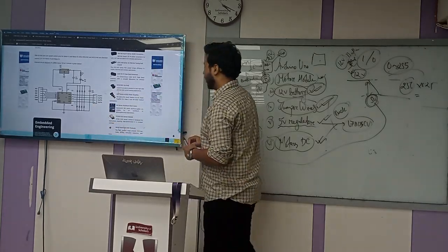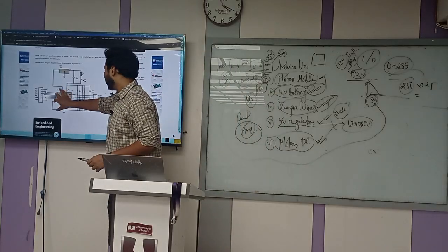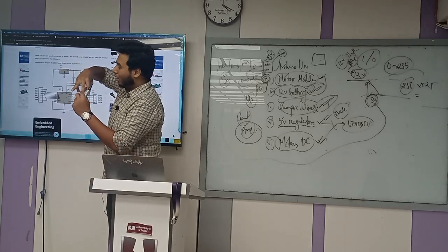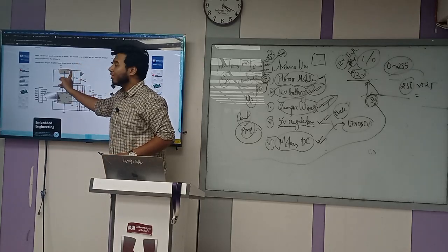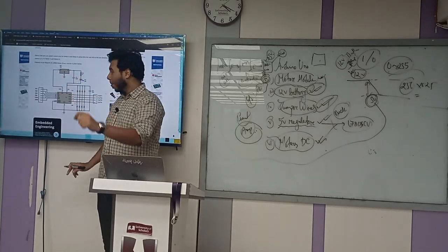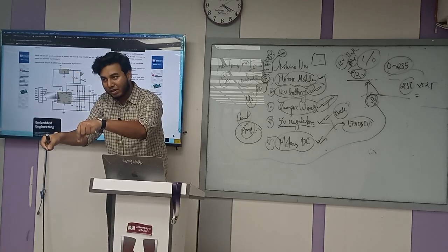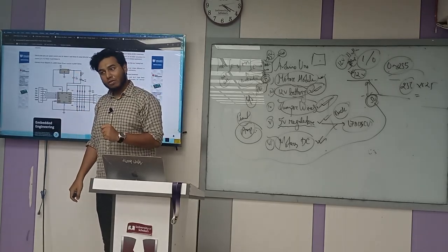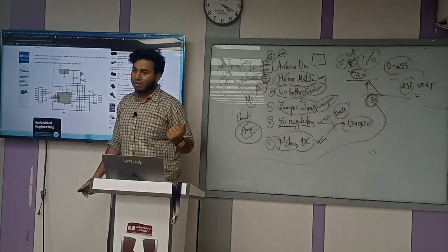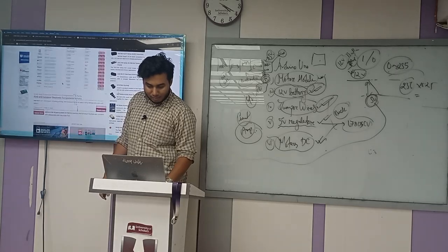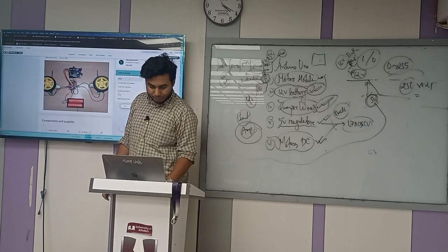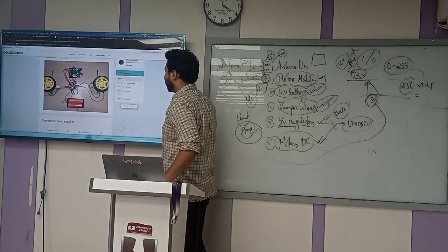Okay, fine. So there are lots of pins over there. You can consider the L7805, which has 3 sections, 3 legs. One is the ground connection, and the others are the input and the output. So the input is the 12 volt, and the output you will measure with the multimeter will be the 5 volt. And the ground is common to everything that is connected to the battery and the multimeter as well. Okay, so that is the section, and ultimately the result will be something like that.